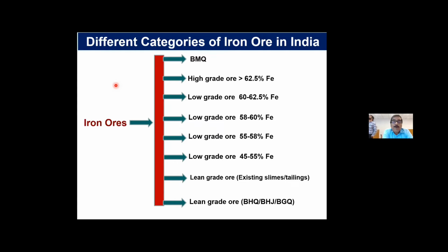But the main issue of iron ore is the hematite ore. If you look at my slides, different industries going for beneficiation and pelletization have different objectives. Some people are looking at super grade pellet, where the input grade of 62.5 is enhanced to 65-66%. Similarly, the lower grade ones go for 63-64, taking 62-62.5 for beneficiation and pelletization. Like that, I have categorized five categories.